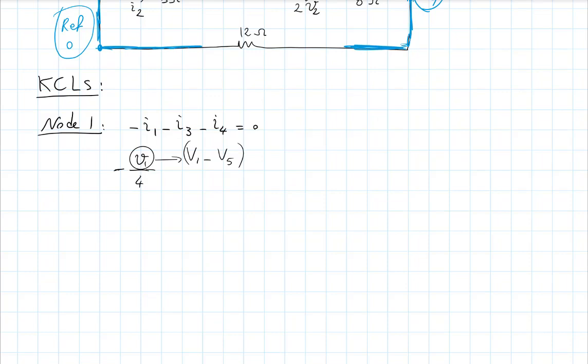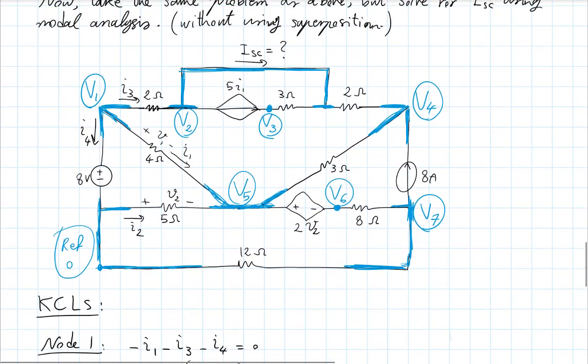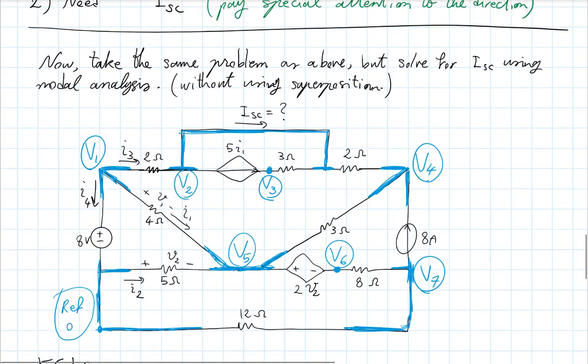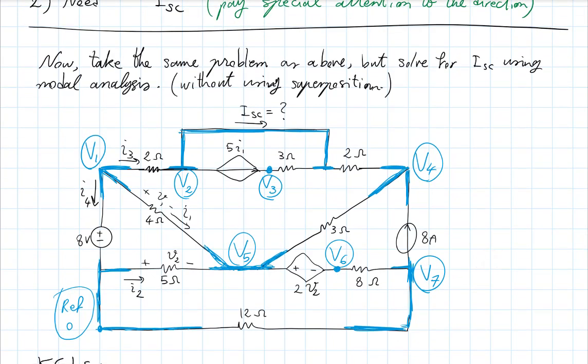So I could maybe now, by looking at this more directly, once I start gaining enough experience, I could say, look, the way I have defined the direction of I1, even if I hadn't labeled the little V1 as an intermediate step, I could see that the direction of I1 is such that the top left is the positive polarity of the voltage, and the bottom right is the negative polarity of the voltage, if I were to write an Ohm's law without a minus sign.